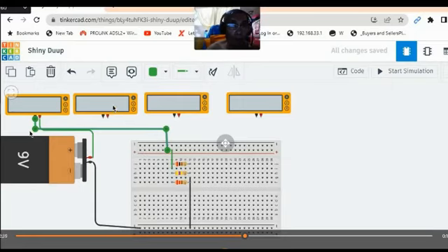And for R1, we also redirect the line here, just following the first multimeter measuring the current of the circuit. The only difference is that we remove R2 and R3, just getting the value of the first resistor.